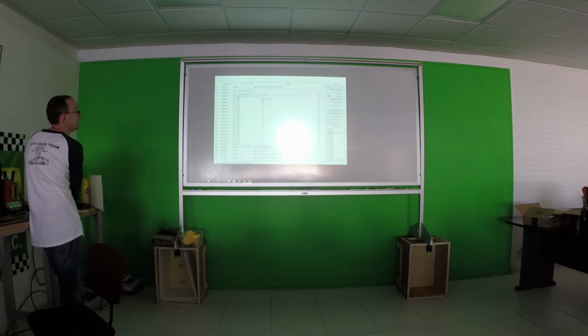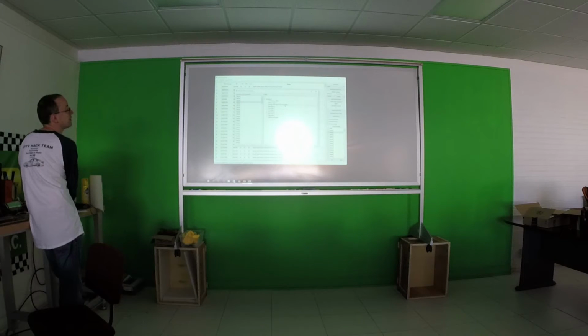This looks at just the loaded data, which was cruise 3. You can see that down here. If I want to see, say, ID 116, it'll tell me how many frames of ID 116 there were and what data length it has. The average interframe interval for this is about 10,000 microseconds, so basically this is sent every 10 milliseconds. Now we can drill in here and find out what values these data bytes had across the entire range of capture.